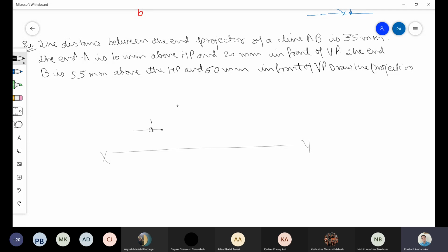And see now, when you are giving dimensions, if you write it like this, A dash here, then the extension line will go from A. So you know that you have to write the dimension here. Where you will write dimension like this, correct? This is how you will write the dimension. This arrow should be closed. See, this is meant by closed arrow, and this is filled. This is meant by open arrow. This is meant by closed arrow, and this is meant by filled arrow. You fill it properly. Okay, this is called closed arrow.